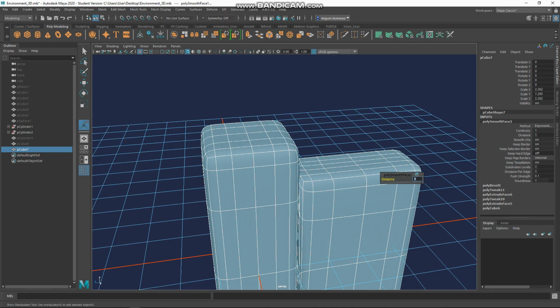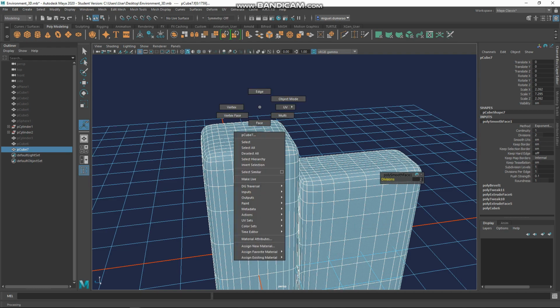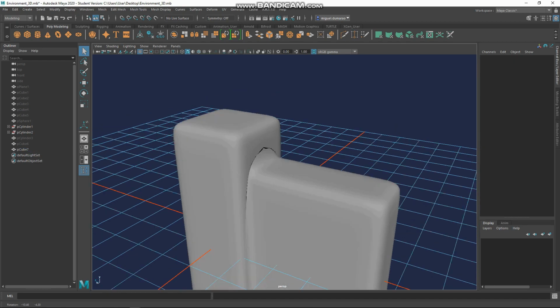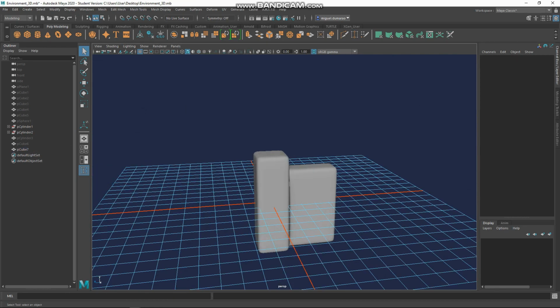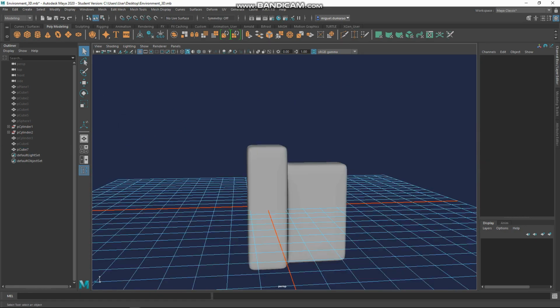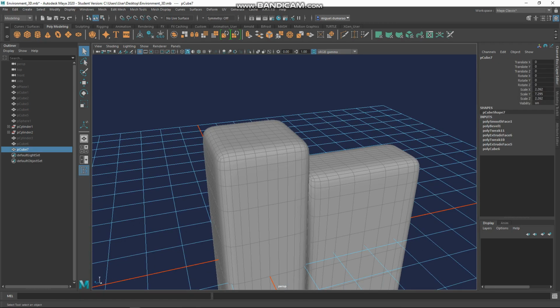You can either go crazy with this, you can go 2 just to make it much denser and hold the overall shape. Now this is your actual shape. If I turn off smooth mode, it's going to retain the shape just like that. Pretty easy. And now you can use this and bake. So that's what I usually do if I do quick baking and try to smooth the edges out, so I could use this information to create maps for my models.